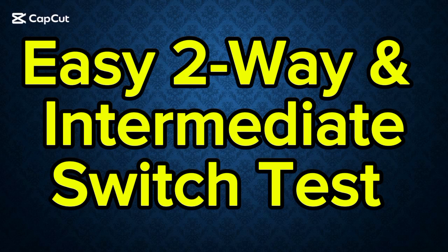Learn how to test two-way and intermediate switches using a digital multimeter step by step. This practical electrical tutorial explains continuity testing, terminal identification, and fault finding for beginners and technicians.